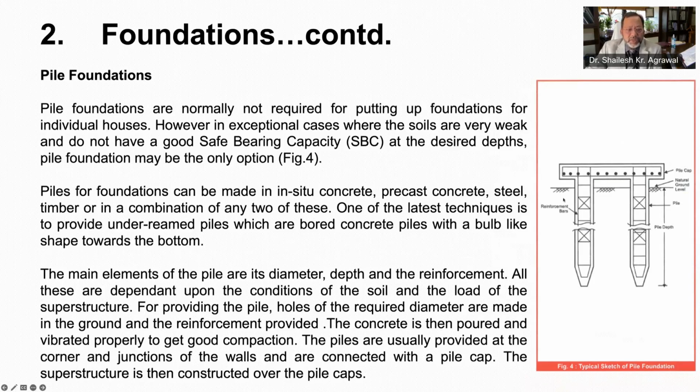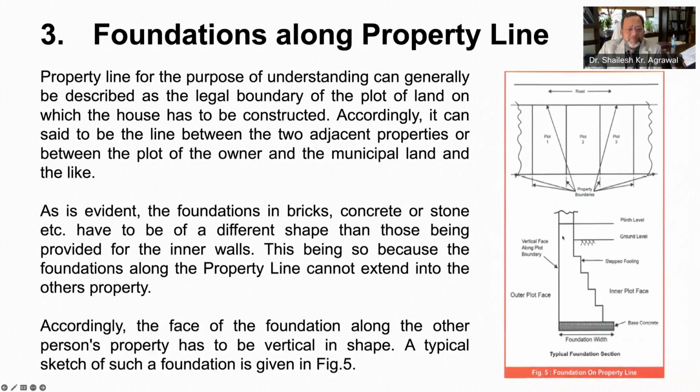and superstructure is constructed over these pile caps. Another very important aspect while laying foundation is that of property line. One cannot excavate and lay foundation in another one's plot, and therefore at the property line foundations are to be provided as shown here in this figure.